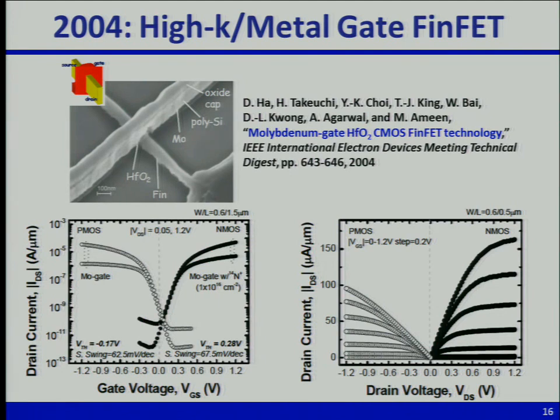Okay. So yeah, the gate work function tuning. Intel does have slightly different metal materials at the oxide interface for N-channel versus P-channel devices. That's how they tune the threshold voltage. Actually, they also implant it.